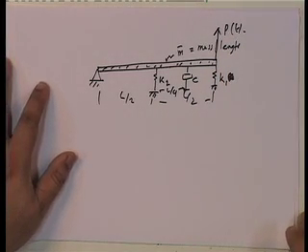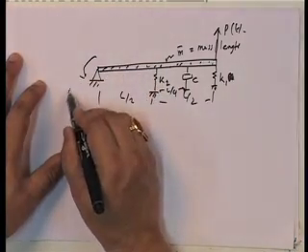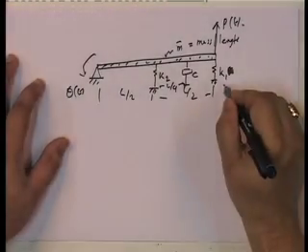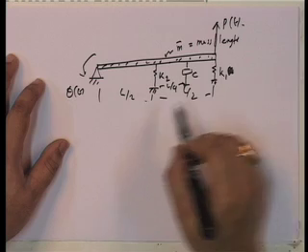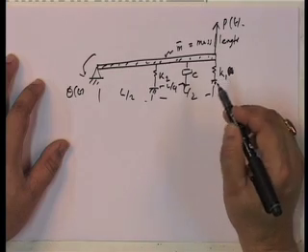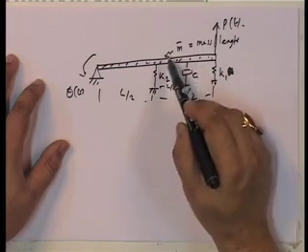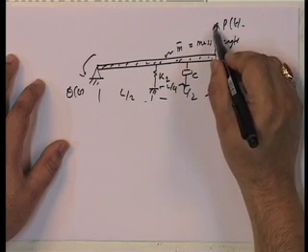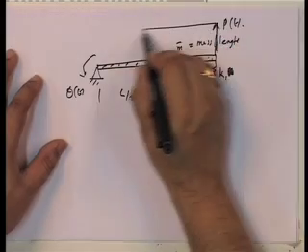So, this is my structure and I am going to derive it with theta t as my degree of freedom, and note that K 1 is the spring here, K 2 is the spring at the midpoint. I put a dashpot here which is at L by 4, and I have m bar as the mass per unit length of this rigid bar, and then I put a concentrated load over here. Well, let me not put a concentrated load, let me just put a UDL.